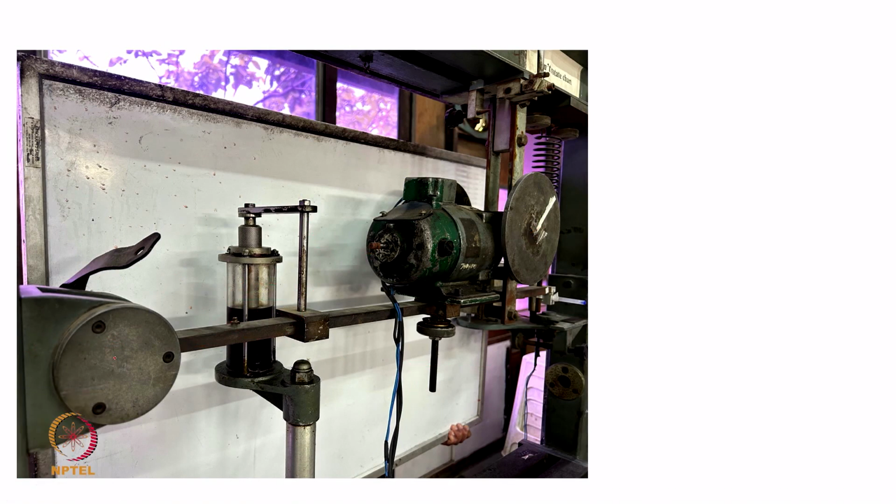So, again you have a hinge, and this bar is nothing but your rigid bar all along up to this point, held by a spring at its end. This represents the mass attached to the beam. This is the dashpot that I meant. There is a viscous fluid in this and the piston, and that creates a dissipating force. These are the two discs that I mentioned. These discs rotate about this axis, which essentially generates an excitation force in the vertical direction, and that causes this beam to oscillate as the discs rotate.